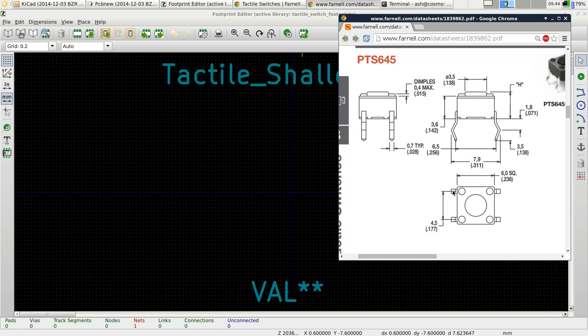and so we can see here that the pins are 4.5 mil apart there. So it's kind of rectangular when looked at from the perspective of the pins. And it's 6mm wide. Now looking at this, there is a kind of a kink there, but that doesn't really matter, because as long as the hole is there, we can push the kink through, and either fold it over or solder it and snip them off or whatever. And we don't really care about the height here in our case.